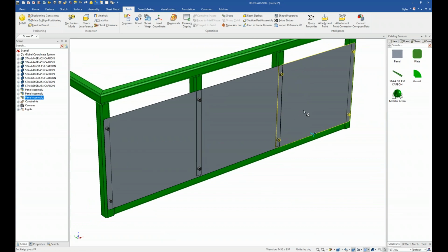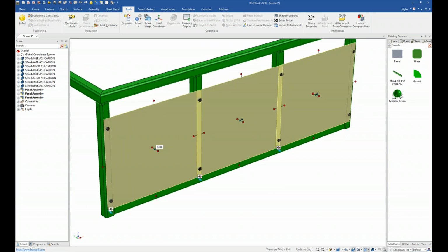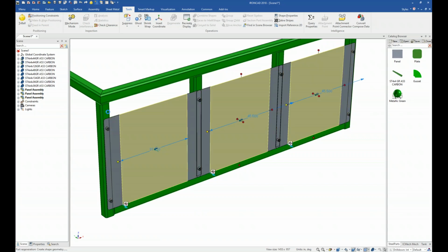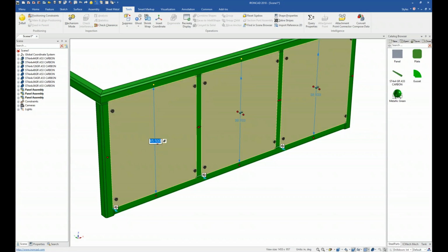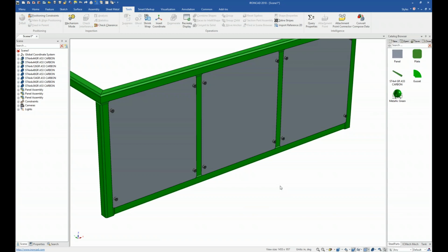We can see that our panels are not quite sized right, so if we click down to our feature level, it's a little bit of an additional intelligence in IronCAD. So if you hold down your shift key, you can multi-select features. And notice these are features within 3 different assemblies and different parts within those assemblies. We can actually pull these handles, and notice if I snap to these locations here, for example, I snap to this location here, all the parts will dynamically adjust, and everything that's tied to those, for example, these fasteners here actually have constraints to where their positions are. Even though I'm adjusting this, all that will adjust for each one of those components as I adjust those.